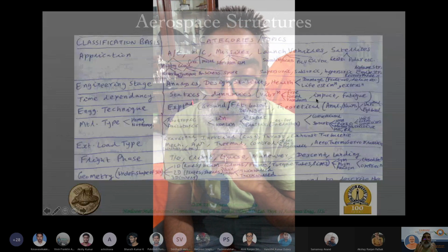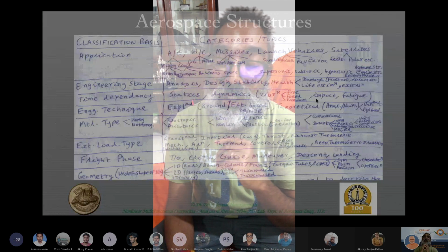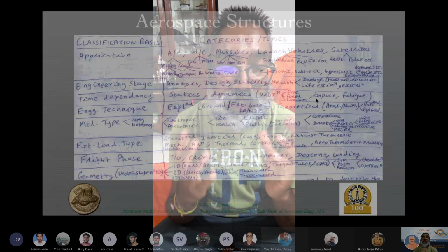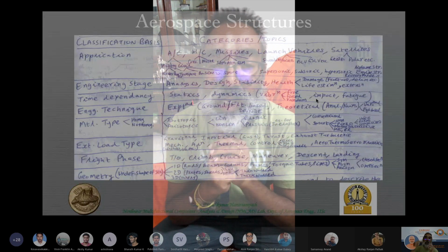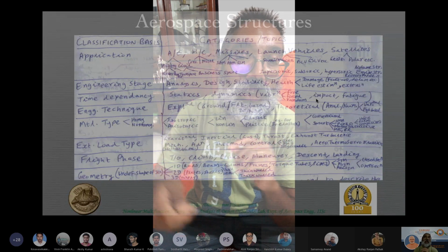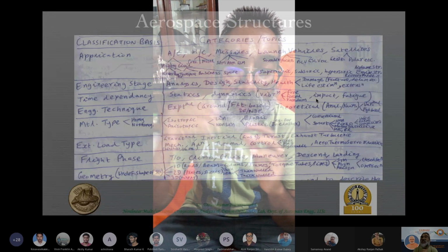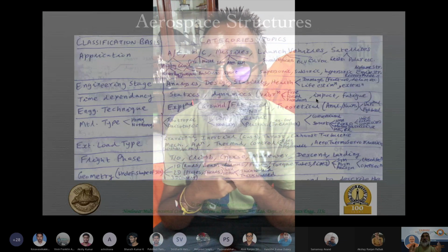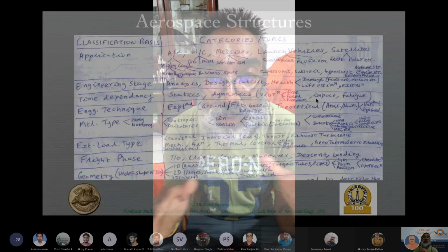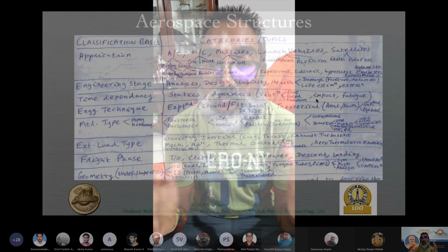So those are all things that impact can study. There are many other types of impact. The bird hit is only one of them. It could be just that the maintenance engineer is using certain tools or drops a hammer on the aircraft that creates an impact damage which may barely be visible. So on a visual inspection, it may not appear.